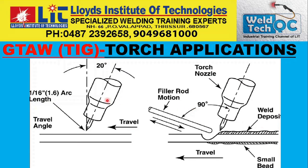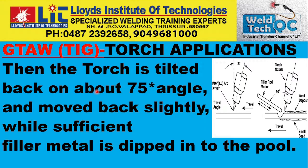Then how you have to hold the torch as well as the filler metal is explained here now. The torch is tilted back about 75 degrees and moved back slightly while sufficient filler metal is dipped into the pool.